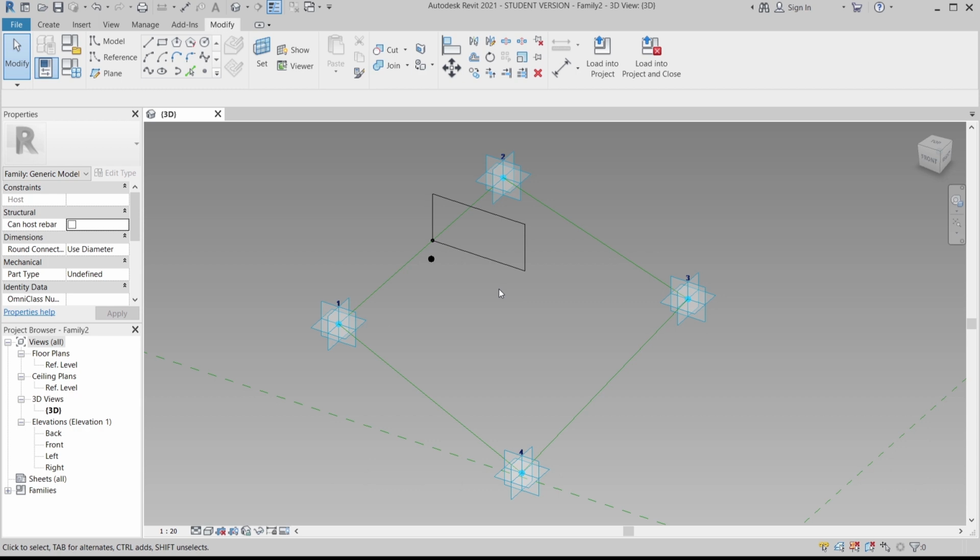Sometimes you put structure, let's say I put a column for the first floor at 300 or 400, but suddenly the structural engineer's calculation shows a different column size is needed for the high-rise building. So I will change it. That's why you need to create a parameter also for your column or for your adaptive components. It's easier for you next round, you just change one and it will change all.